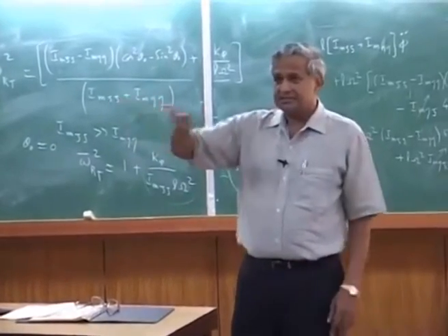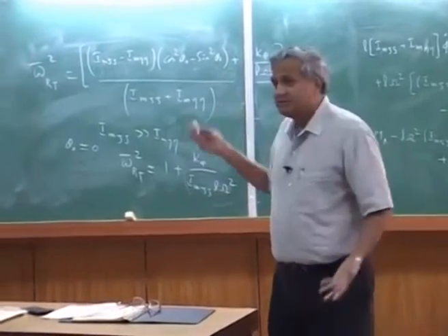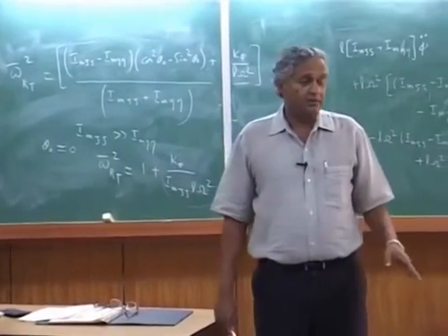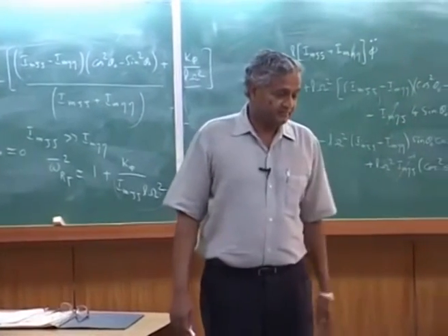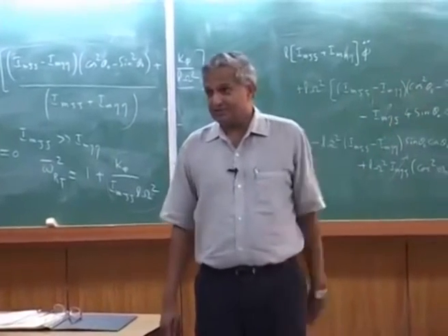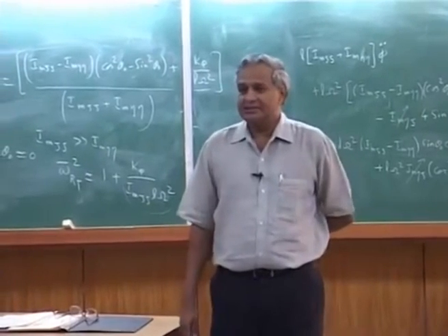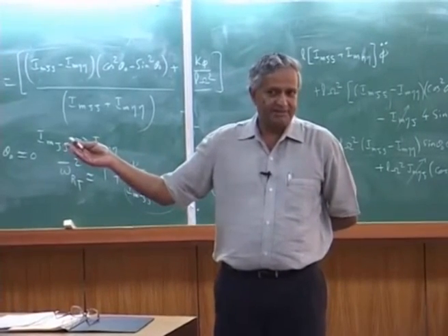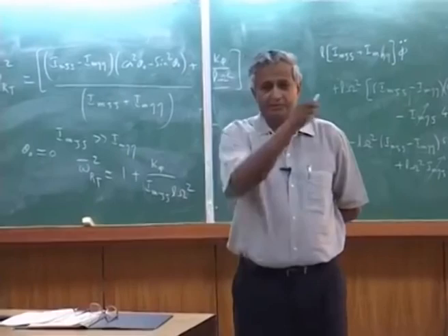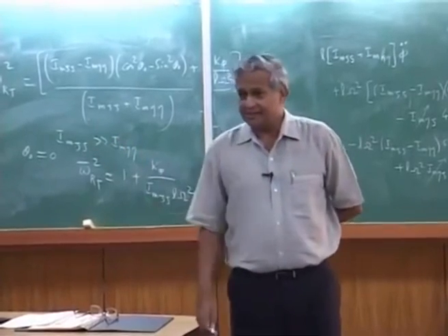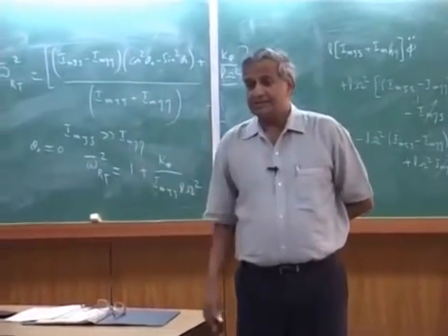Only thing is, what is the effect of the centrifugal load? In flap motion you consider, lead lag motion you consider, torsional motion you consider. But if you say, no, I want to include elastic deformation in axial direction, then you write the axial equation. Then there are certain approximations made, which is usually what you normally make in traditional bending problems. What do you do? You draw a line, a reference line, and then it deforms. You see the length of that line does not change.